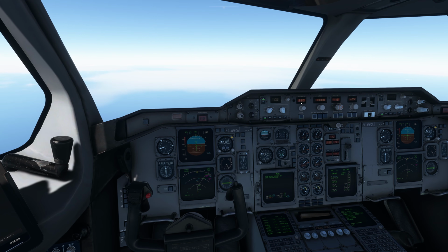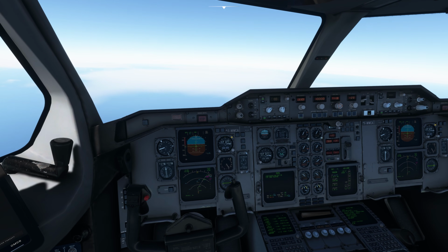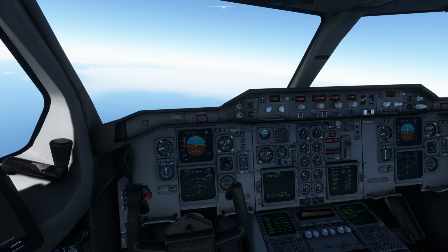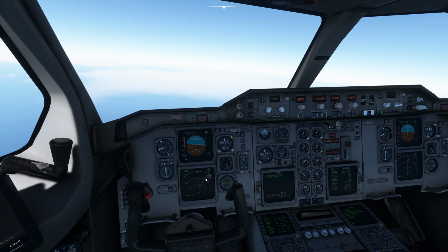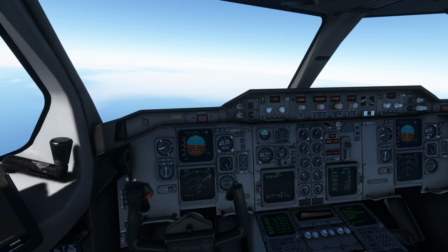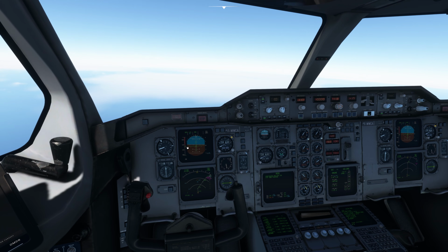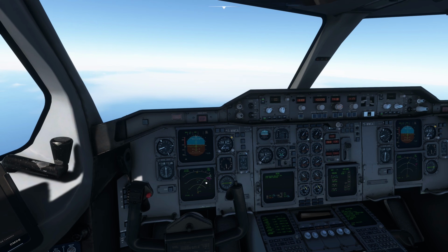It cannot go below 330 knots, but it can go more than that, because if I have a steeper descent. Now you see this arc coming over here. Now the navigation display is a very good indicator which tells you by which point you will be at the given altitude. So right now, as you can see, the descent was a very aggressive one, so I have good ground to cover. I can be at 10,000 feet by this point, so I can really adjust the vertical speed in such a way that the speed doesn't increase and it remains in a normal threshold.